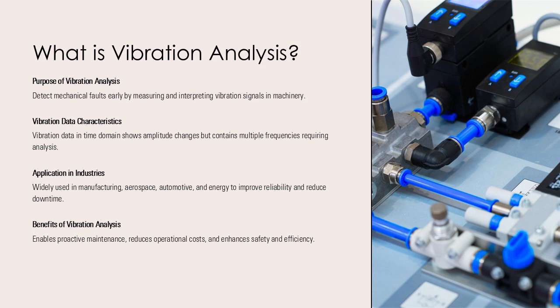It involves measuring and interpreting vibration signals to detect imbalances, misalignments, bearing failures, and other mechanical issues before they lead to catastrophic breakdowns. Vibration occurs when a machine or component oscillates around its equilibrium position, and these oscillations can be recorded using sensors such as accelerometers.